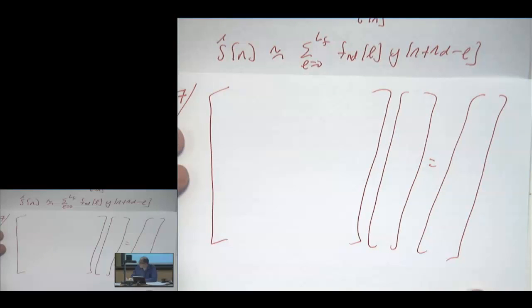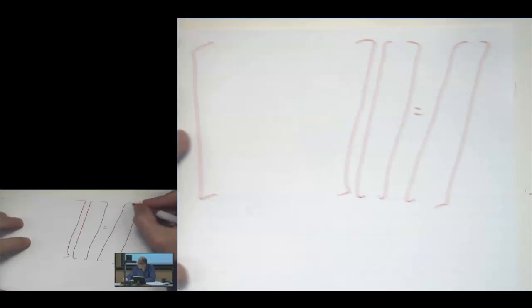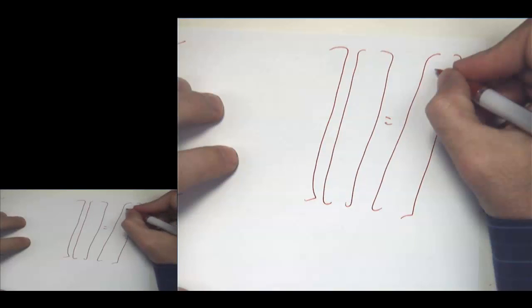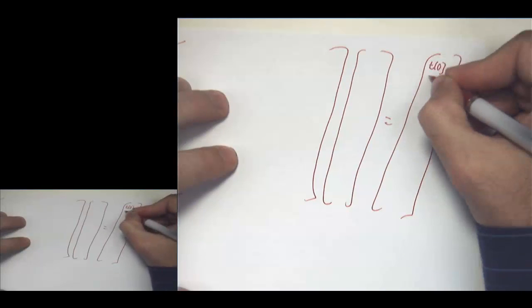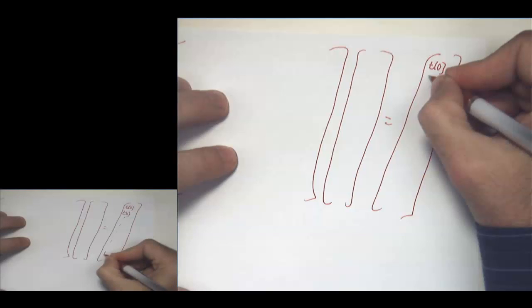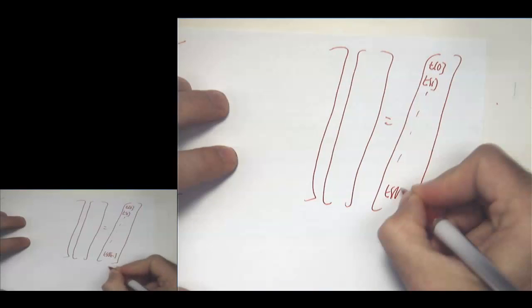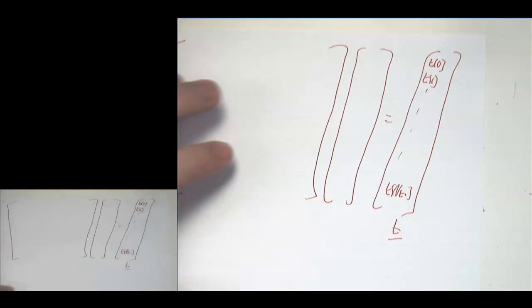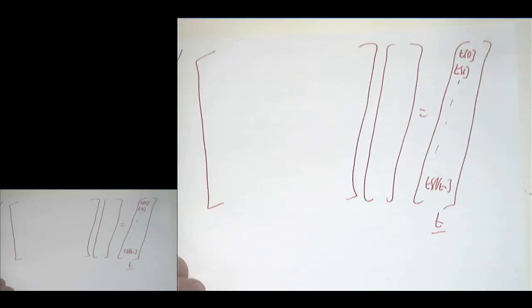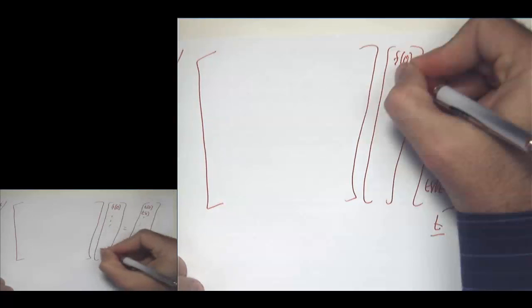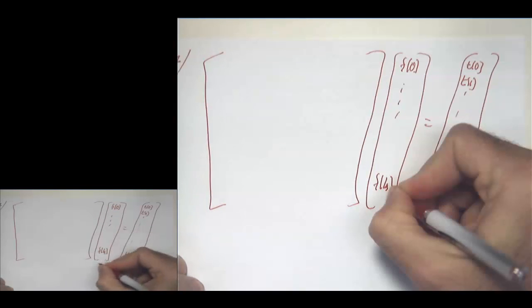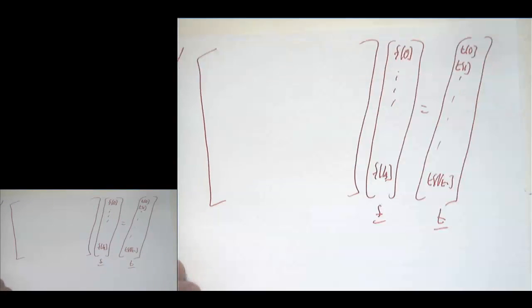Wow. It's a lot of distortion up here. So let's put over here what we know. That's t0, t1, down through t of nt minus 1. So that'll be our t vector there. What we don't know, the coefficients of the equalizer, f0 through f of LF. That'll be our f vector. And then all we have to do is populate this big fat matrix here.